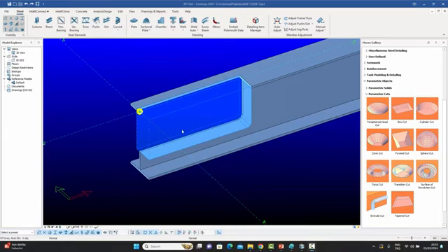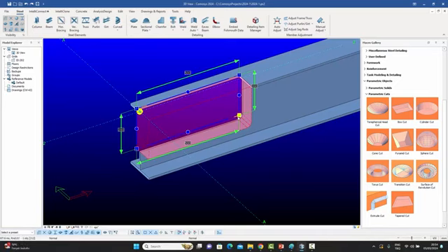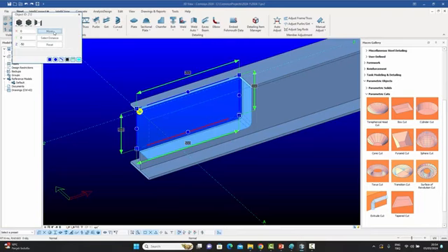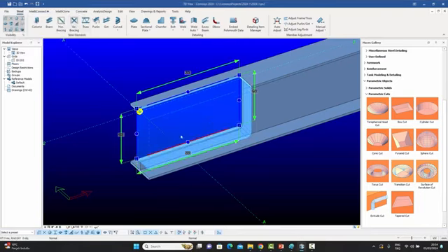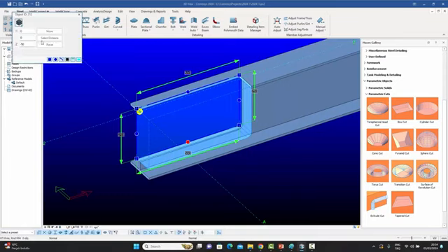So just like I showed you that by selecting this tapered cut, you could give chamfers to points, you could also move the entire definition lines. So I can take this entire line, for example, and say move it downwards by 50 millimeters. Or what I could do is select this point only, and this point doesn't exist. It's the midpoint, and I can create a new definition point by adding a new vertex to this cut.